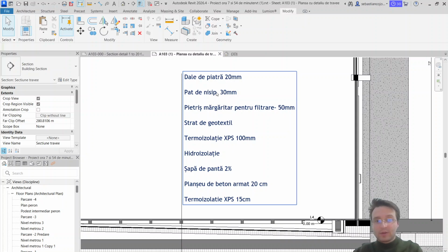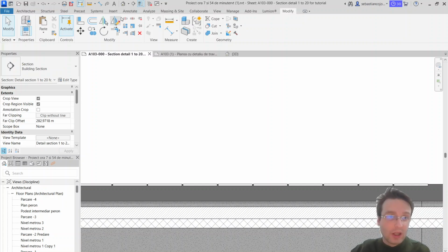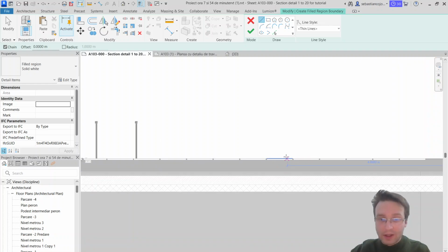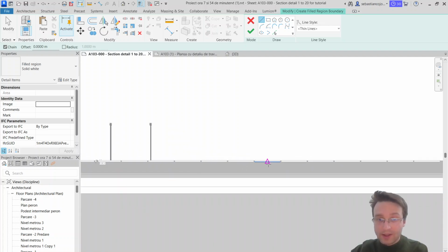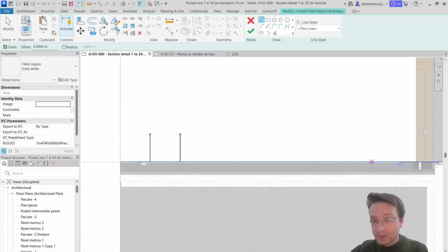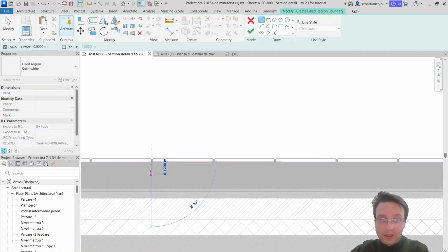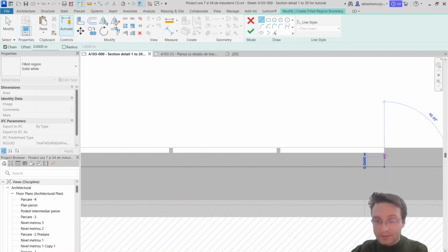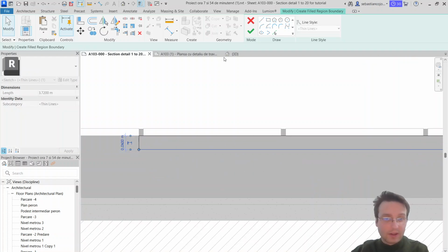Okay, then I need a bit of sand, so I'll mention that I need a sand layer, and let's do the filling region. Annotate fill region, we have this sand layer. I think the detail will be split into the normal detail, which will be something like this and can be done as a slab, and the custom detail, which is something like here. So let's say I have my sand layer, something like this. It will be, let's say, 5 centimeters deep or something like that.